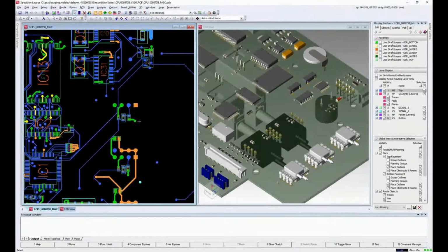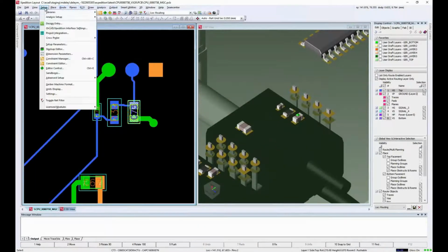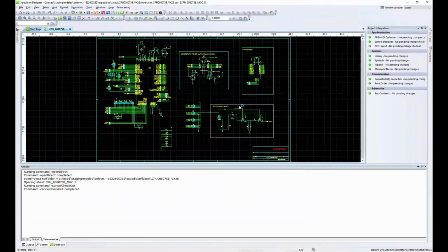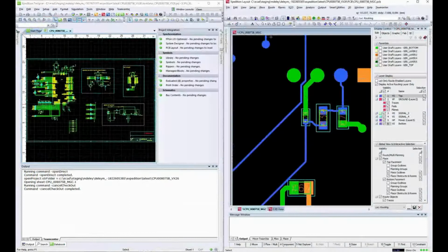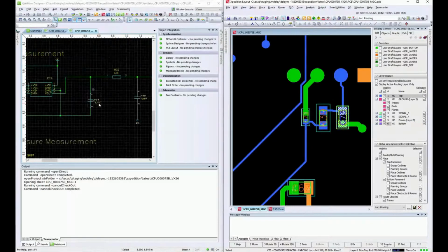As in the previous session, I want to make a change around the pressure sensors where I know I need to add a filter component. Here I can zoom in the design area and visually check where I want to make my changes in both 2D and 3D. And select the component and open the schematic to very quickly use cross-probing to drive the design from layout into the area of the schematic automatically where I want to make my changes.